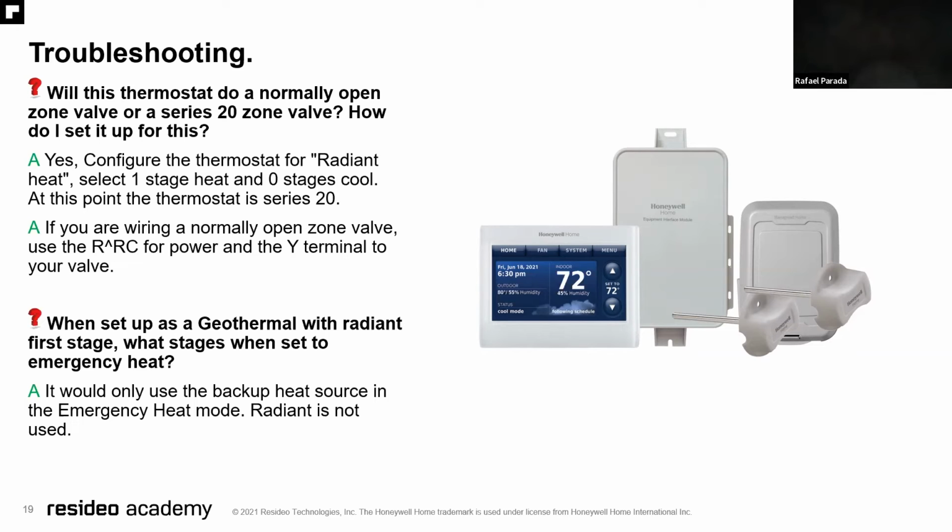Will the hot water run? And the answer is no. It will only run the backup heat that is configured. It could be either electric, gas, or oil furnaces. So whenever I set for emergency, those ones are the ones that are going to run. The backup ones, not the hot water that was set for first stage.